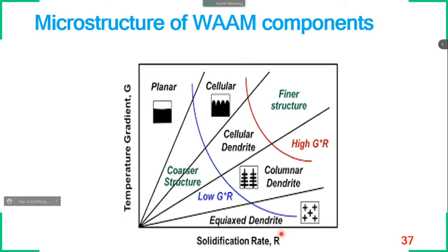Okay, so how fast a metal can solidify determines how the microstructural evolution can happen. If powder-based additive manufacturing is concerned, the solidification rates are very, very high, like 10^5 Kelvin per second or 10^8 Kelvin per second. Such very high solidification rates can happen in powder-based processes like selective laser melting or direct metal laser sintering, 10^5 to 10^7 Kelvin per second.